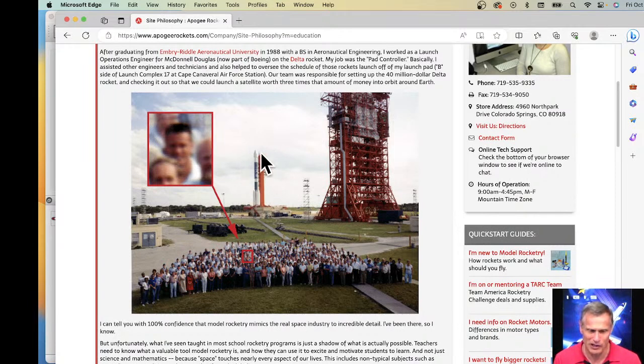And this tower here that's so nice and pretty orange, it would turn solid black every time. And then a crew would have to come in and sandblast it all down. Because it's the weirdest thing, what happens is the metal instantly rusts because it peels the paint off, and then there's bare metal, and it's kind of like you sandblast some metal and you come back a few days later and it's all rusty.